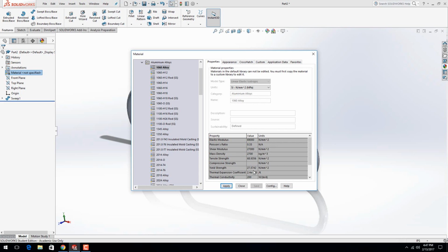The yield strength is essentially when something bends and it passes that yield strength barrier and it no longer bends back into place. Anything below it is called elastic deformation, meaning it'll snap back. Anything past that is called plastic deformation, and it no longer snaps back. It may not break, but we still might consider it failure because once something is bent, it may no longer be of any use to us.